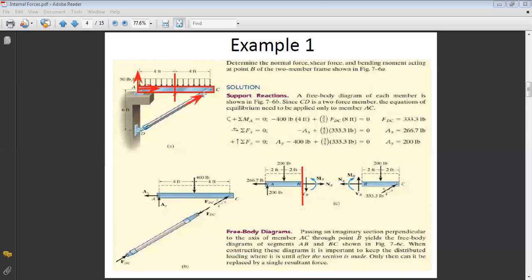This is the force at C. So now I have three unknowns, which are AX, AY, and the force at C, FC. Since I have three unknowns and a 2D equilibrium problem, I can write the three equations of equilibrium for part AC.